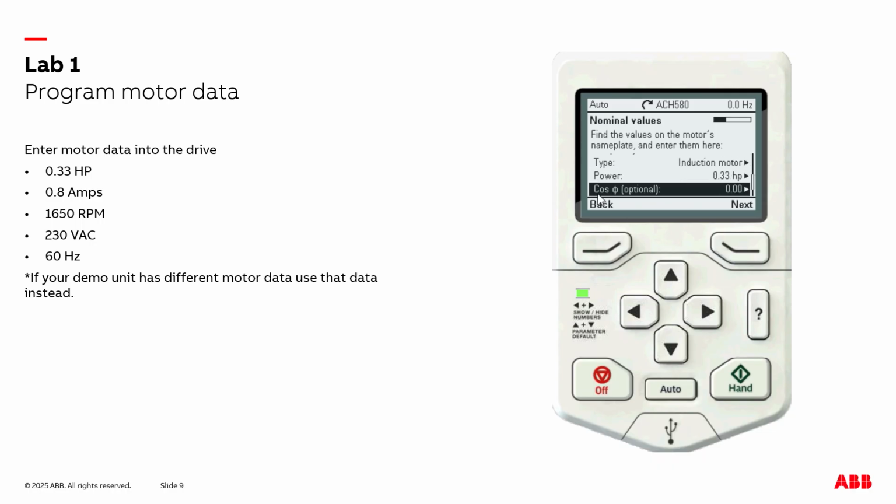And we can disregard the cosine phi, that's optional, and also the torque. So now we can hit next. Now we're also being asked some information about the application. The minimum frequency is 0 Hertz. The maximum frequency is 60 Hertz.